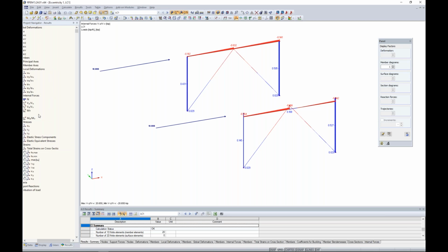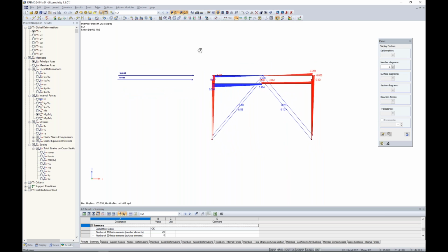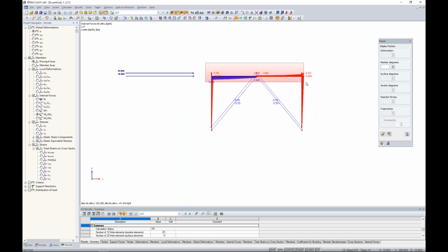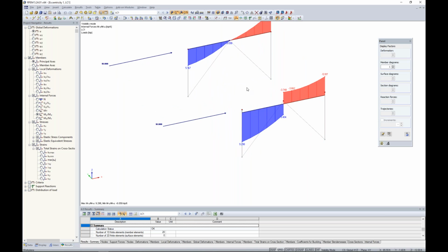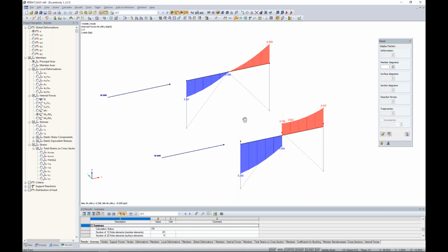But taking a look at the bending moment, the strong axis bending moment, let me create a visibility for just these two upper beams here. Well, you'll notice the drastic difference with the strong axis bending. In my first example, we transition here from a positive moment, 0 moment at the midspan, into a negative moment. Quite a different story when we've taken into consideration that eccentricity. So we have a huge jump in the moment where those chevron braces are framing in.